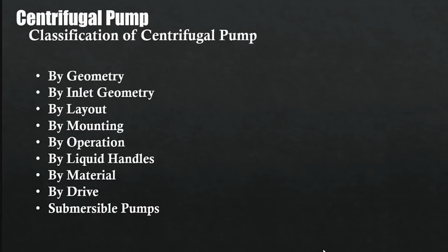active or corrosive fluids. The next is the by drive. This specifies the method of drive intended or applicable for the pump as specified in the design, mounting, area limitations or other requirements to use. The last classification of centrifugal pump is submersible pump. Pumps of this type are of sufficient importance to warrant a classification of their own, representing the type of pump with an integral electric motor which can be immersed in the product being handled.